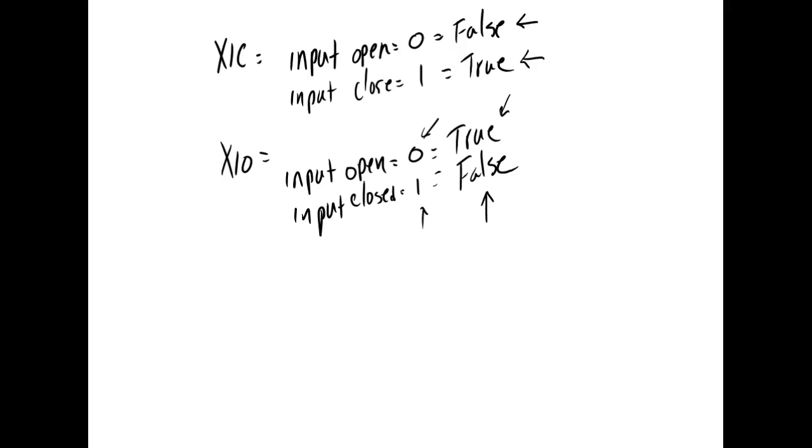Which gets us a little confused, because in motor controls we use a normally closed contact as a normally closed symbol. Right? In PLC, we use a normally open contact symbol for a normally closed push button. Do you understand that? If I use normally open push buttons, then I have no problem. I just say I use a normally open symbol, right? Because when it's released, it's false, and when I press it, it's true, so it's going to change settings.